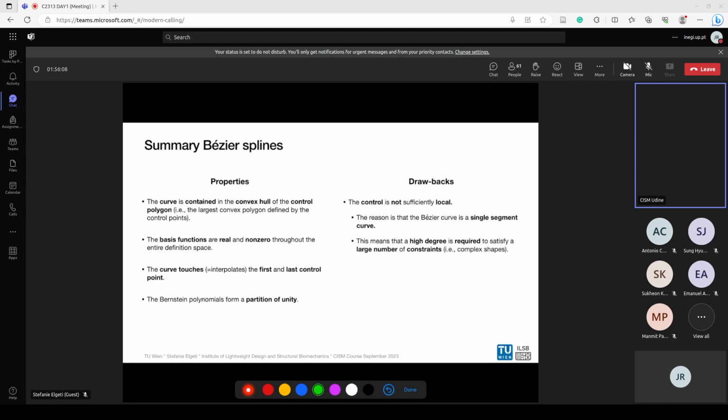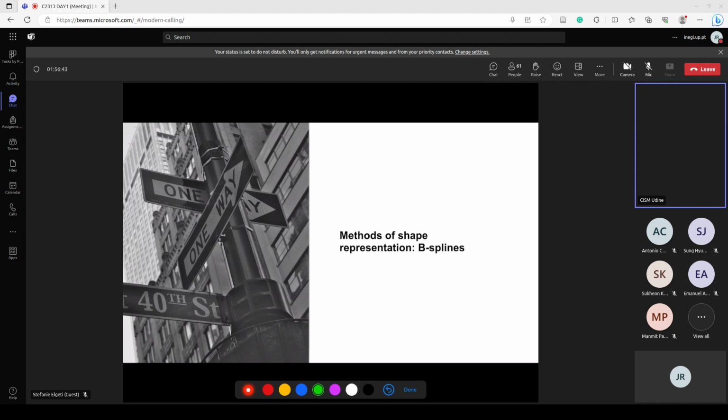Namely, I'll just tell you. There are important types of curves that cannot be represented using Bezier splines because we have polynomial basis functions, so we cannot represent conic sections. So no circles, spheres, cylinders, all of these things, which in turn are very important in engineering. We saw, for example, we don't want the stress concentration, so we want a radius. Now with the Bezier spline, we cannot represent the radius because it's based on polynomials. So this is why they're no longer used in CAD systems.